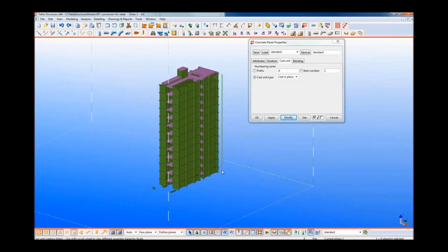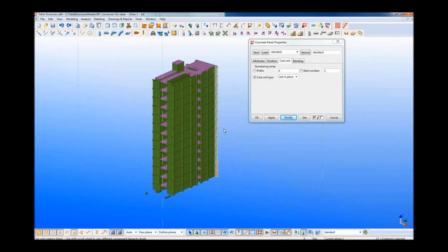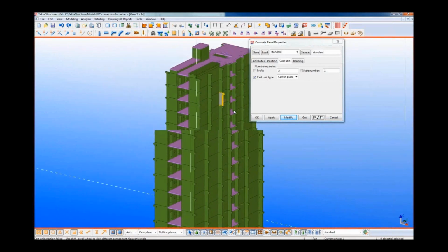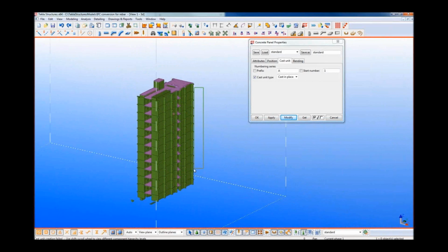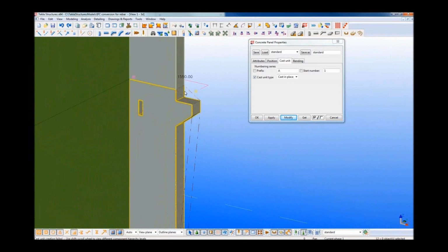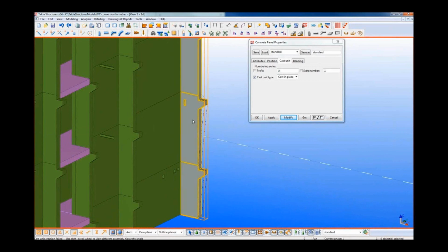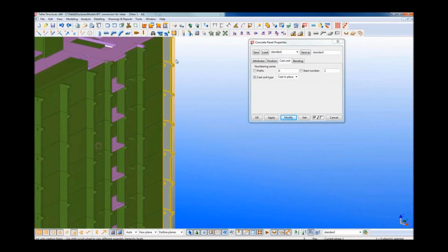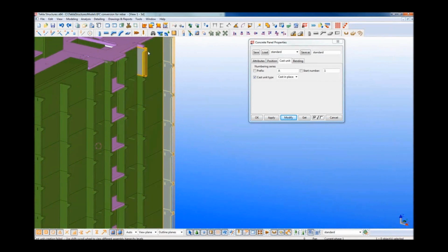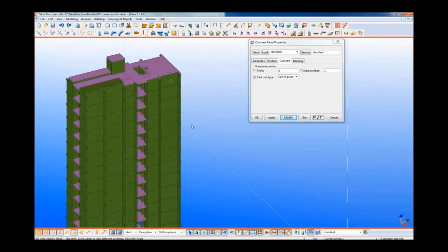We can do the same for this wall. So we can take this and, apologies, pick something we can't pick there. I just picked a cut accidentally, so cast unit, create cast unit, and again, so then we'll be able to have a nice elevation on this wall showing all the reinforcement, a nice elevation on this wall, and we just go through, and it's all about just grouping into which parts of the reinforcement you want.